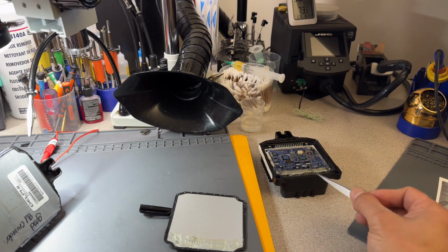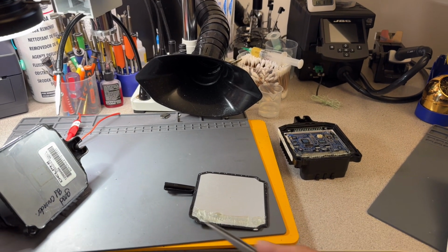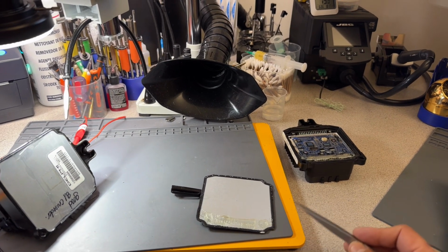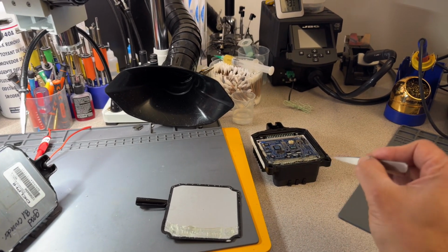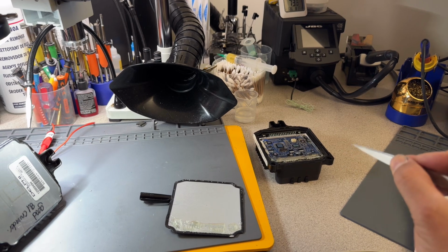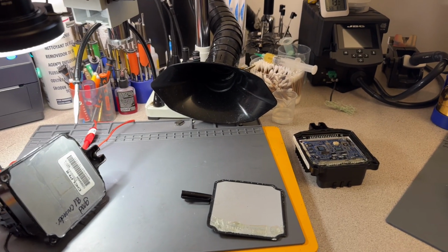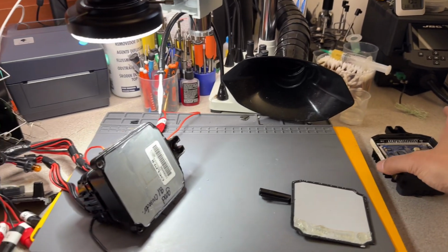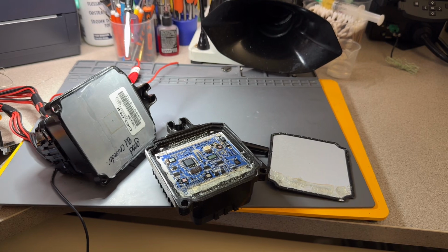These are the wires that usually break because of this situation. So I'm going to clean this over and try to stop that from happening in the future. But for right now, I checked all the jumper wires, pulling them slowly and softly, and none of them are broken, and the computer is all good. I checked, there are no signs of corrosion, no signs of burn, sensor ground, power, everything is good. So, David, your computer is good to go.